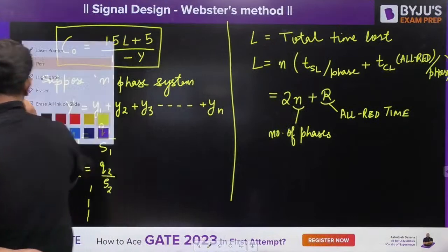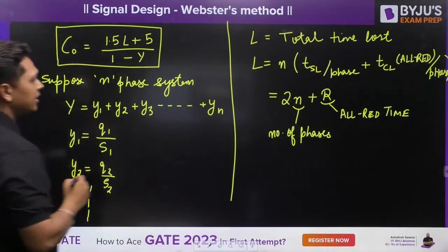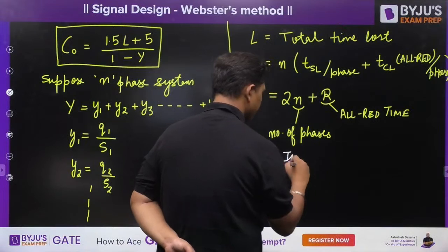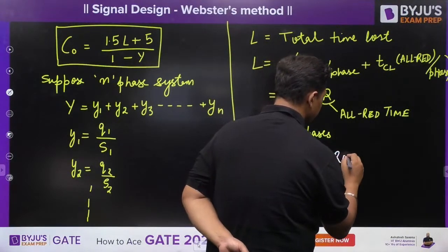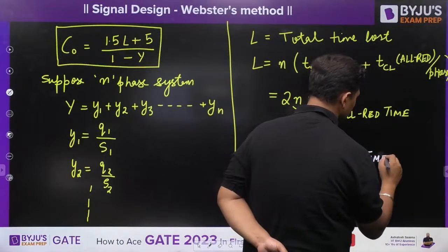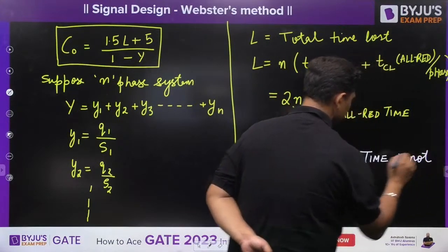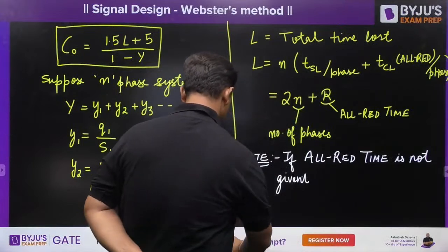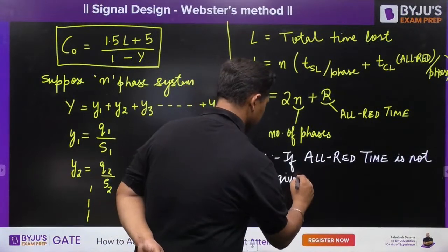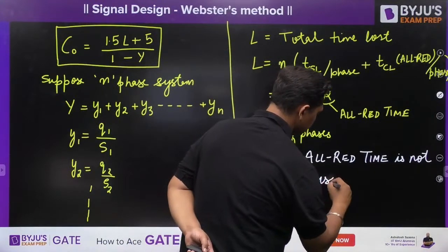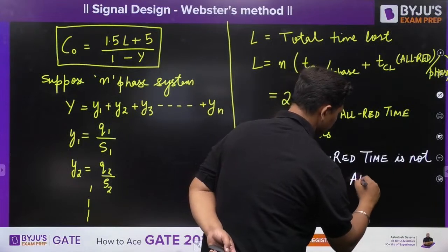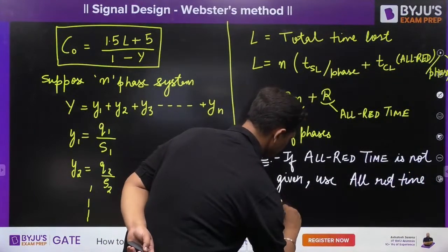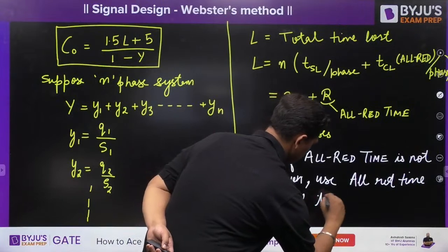One note point over here. If all red time is not given, use all red time equal to amber time.